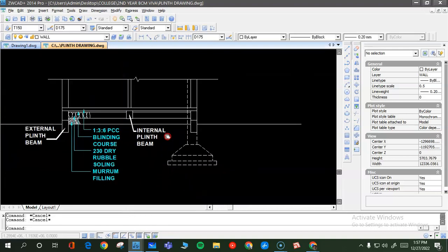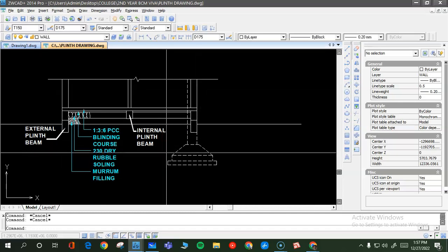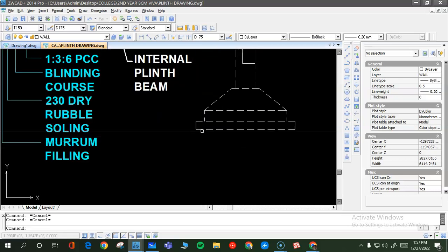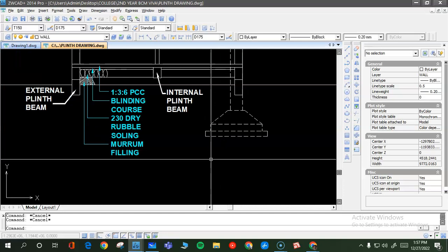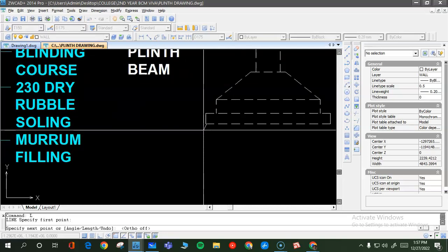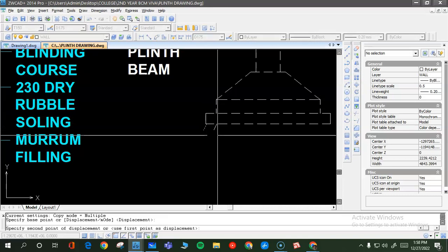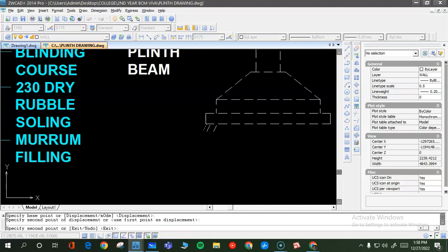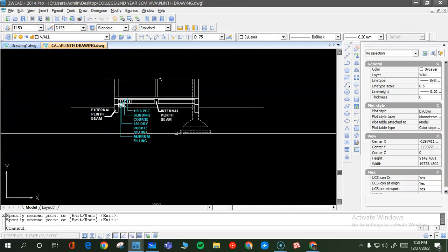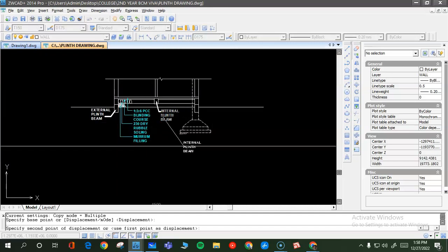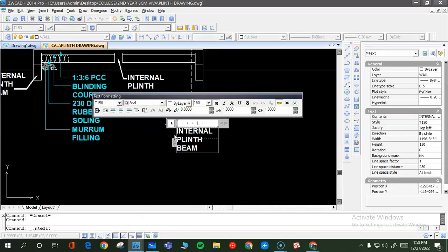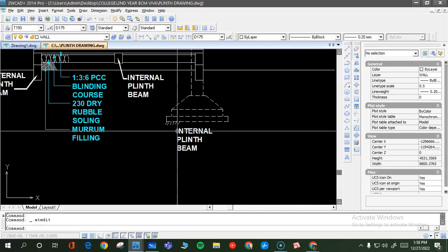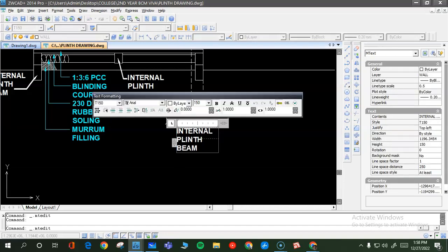Okay. And indicate wherever brickwork is there, wherever concrete is there, indicate it properly with the required indication. Below this you can just simply show these lines like this, and you have to write here hard strata. So you can go on copying them like this and indicate this as hard strata. Right here, hard strata. All this drawing which we have mentioned up to now will all be drawn with the help of 1:50 scale because that is what they have asked you.